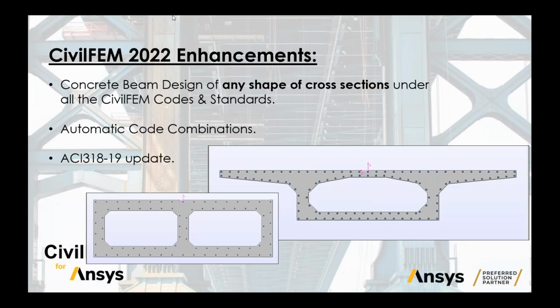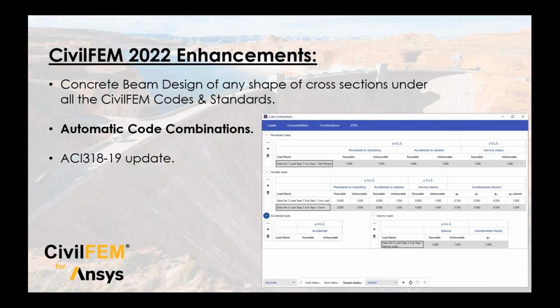But we are going to focus on the bridge, and continue seeing those options. These are the cross sections that we are using for this bridge, and we have predefined a minimum reinforcement amount in all the phases: reinforcements of 12, that is rebars of 12 millimeters diameter, with a spacing of 30 centimeters. That is the minimum reinforcement amount, and we have placed it around. So CivilFEM will increase the reinforcement groups that will be needed to fulfill the codes.